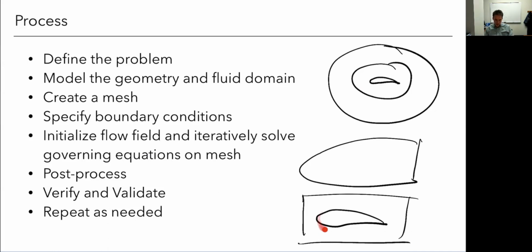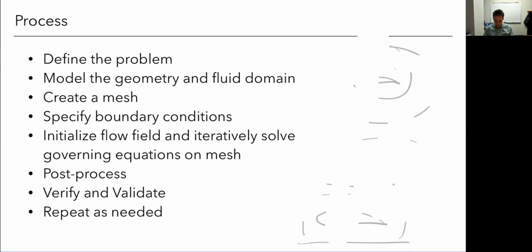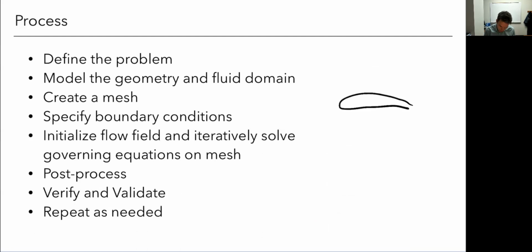But in all cases, again, usually the mesh is getting bigger and bigger, so it's not that hard or that expensive to just go ahead and make the boundaries bigger, right? Like go to 10 times the body size and then you'll be safe. Because what happens is the mesh grows, as we've seen. So near the body, I'm just going to draw this horrible mesh, right? The mesh size needs to be super tiny because I've got to resolve all these tiny features.